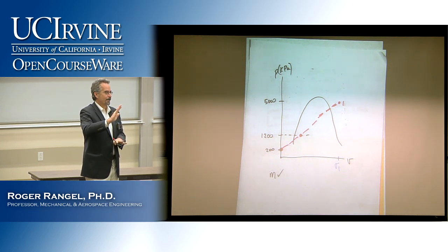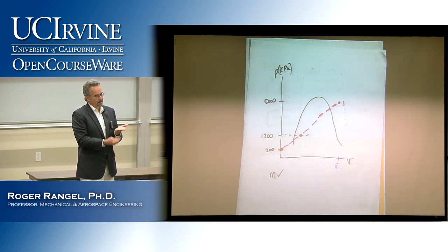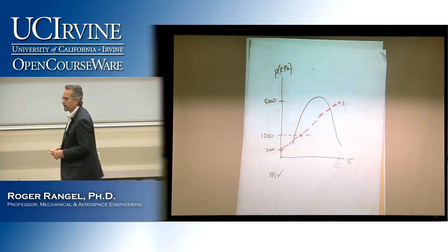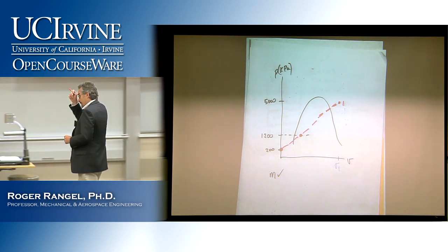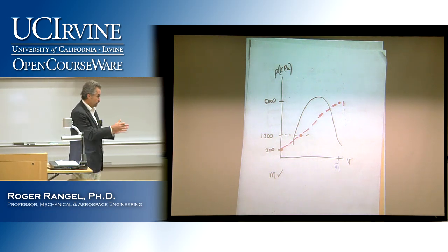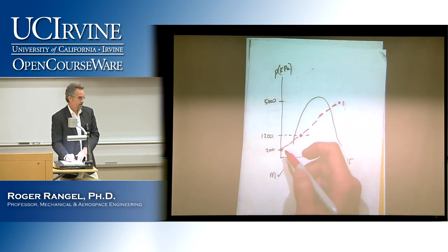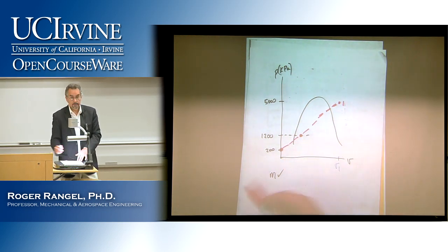That's it. We haven't seen the empty cylinder, but we're told that in the setup that we're working with, if the piston is sitting at the bottom, I need at least 200 kilopascals of pressure to push that piston up. So that piece of information is the extra piece of information that has nothing to do with our actual process, but allows us to determine the slope of the process line.